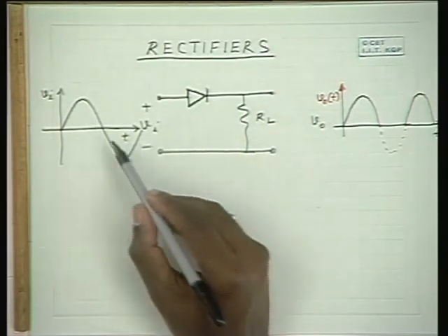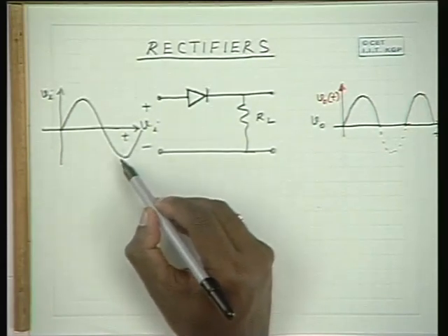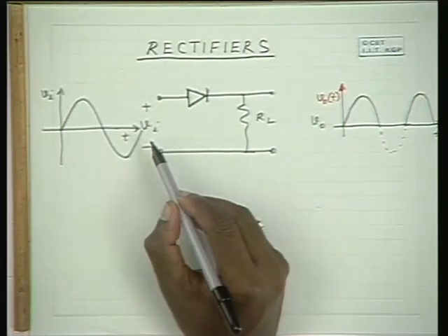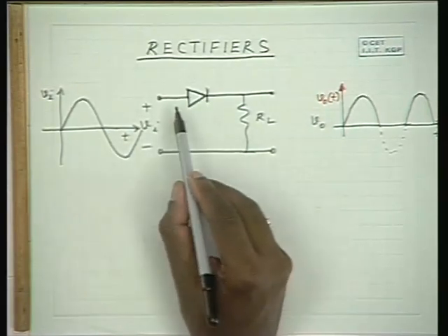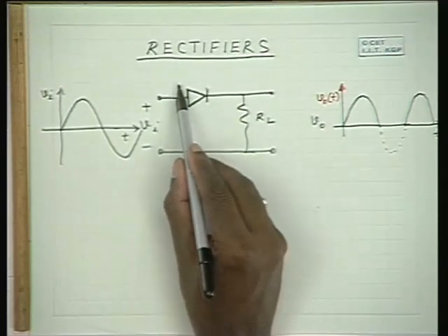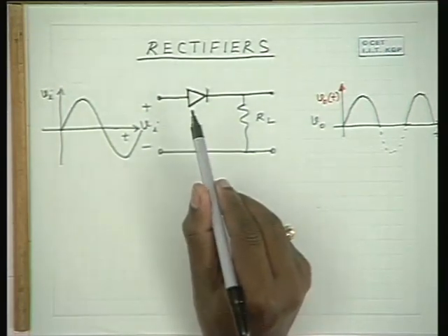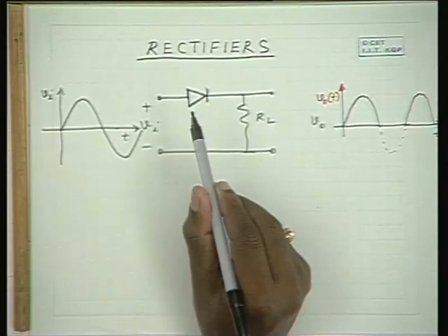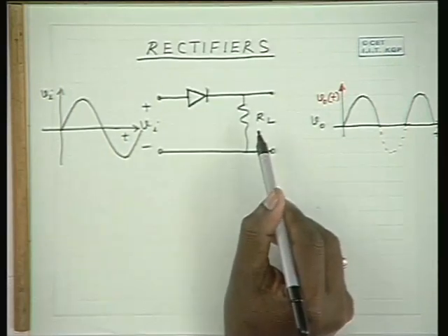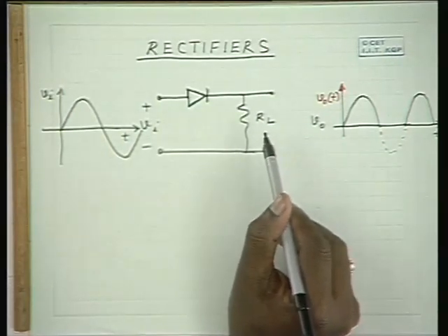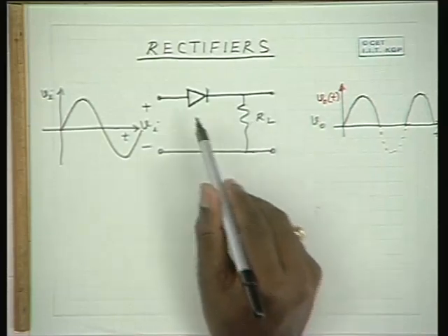As long as this reverse voltage is less than the breakdown voltage, what is allowed by the diode is that reverse saturation current, which is of the order of 1 nanoampere in the case of a silicon diode. So, with 1 nanoampere current passed to the load, it is a negligible amount of current. It is almost that no current is passing to the load.